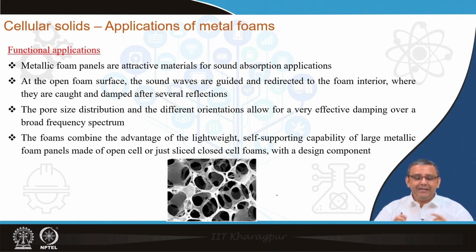Why? Because this open cell foam provides good permeability, because the pores in this open cell foam structure are all interconnected. That means ideally if you enter from one side, and if the medium is thin enough, you can pass through and get out from the other side of the material. This is the open cell structure. All the parts are interconnected. At the same time, the path is extremely tortuous.